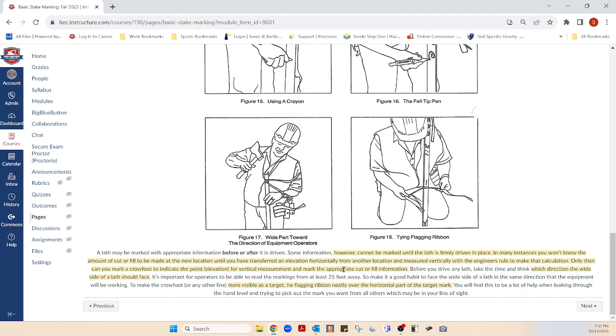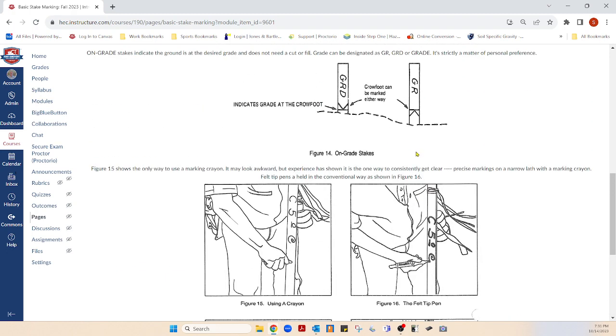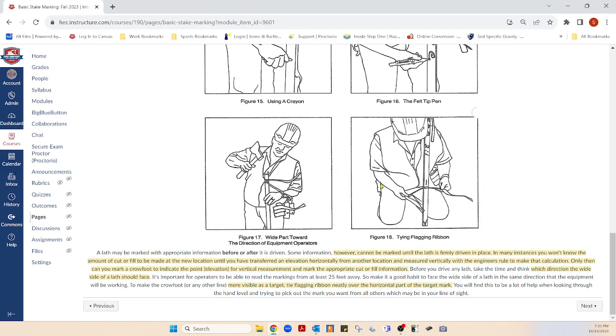This may clarify it a little bit better. It talks about 25 feet away, because that's usually the maximum range of an accurate shot with a hand level. When you have an error using a hand level, it's usually because it wasn't level or you didn't read it right when you shot it.